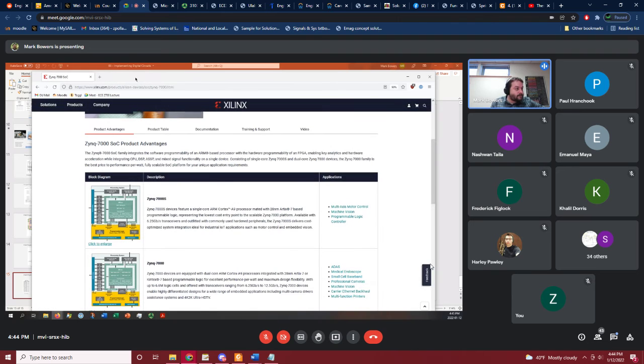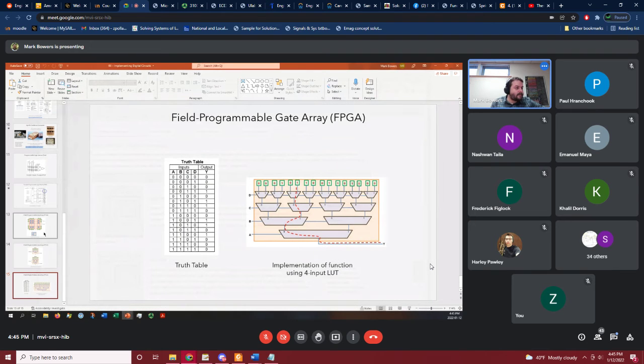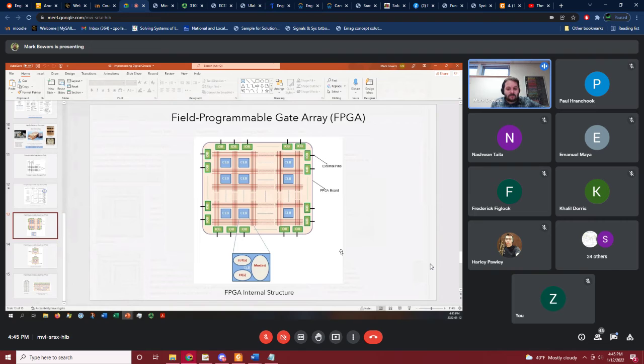The other thing you can do is, remember, for an FPGA, you can make pretty much any kind of logic with it. So you could also make a whole microcontroller. You can make a whole processor and implement it within all these lookup tables and interconnects. If you want a microprocessor, you can make it on an FPGA, and we'll show that by the time we get to the end of the course. You'll be able to make a little tiny processor of your own design and implement it here with all the logic cells and everything.